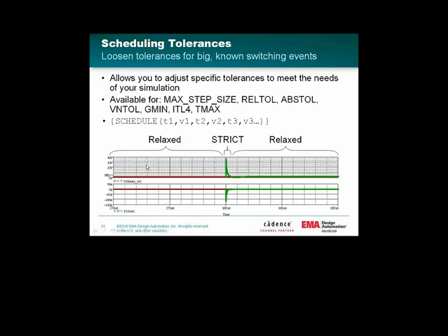So in this example right here, this might be a circuit simulation where if you run this one along here on the X, you would be cruising along here, and all of a sudden right here, you'd get a non-convergence problem. So you'd get a spike in your simulation results, and it might say it can't converge past that. At which point you would try and maybe loosen your tolerances and try and figure things out.